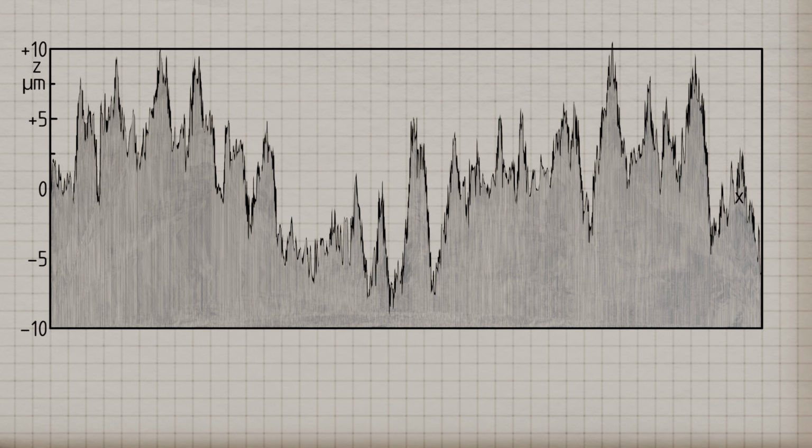or R. Note that the present surface profile strictly speaking does not yet represent a primary profile, as it is still superimposed by noise. Exemplarily, these short wave oscillations can be seen in the diagram as the jitter motion. The example shown fundamentally illustrates that choosing the correct filtering plays a central role in determining roughness parameters, since otherwise the roughness profile still contains components from other influences such as noise, waviness, and form deviations.